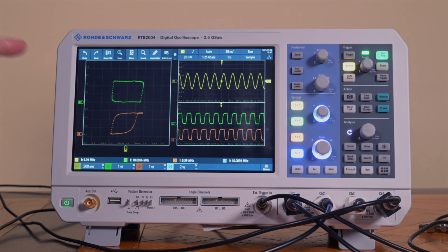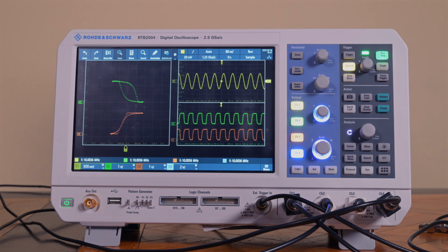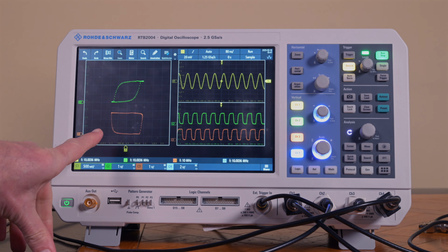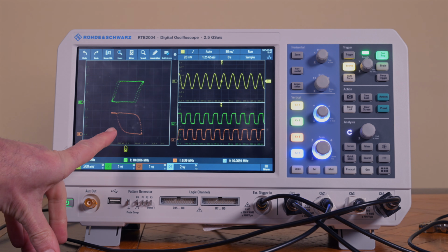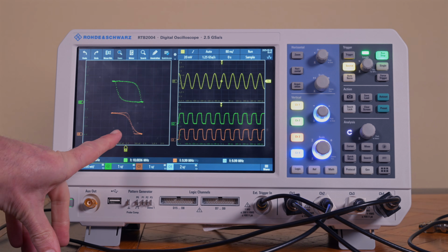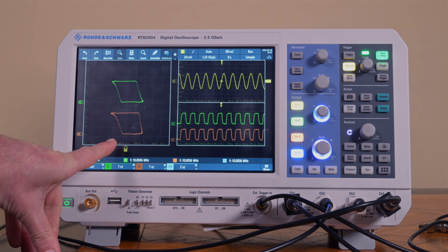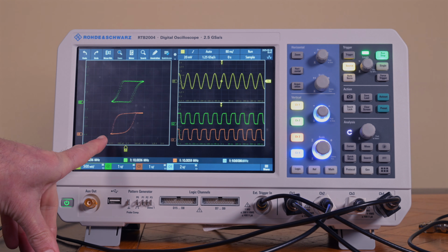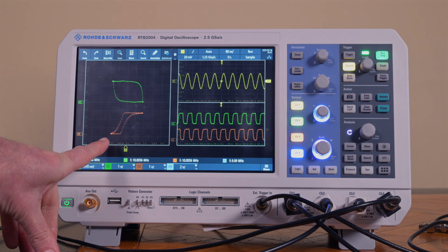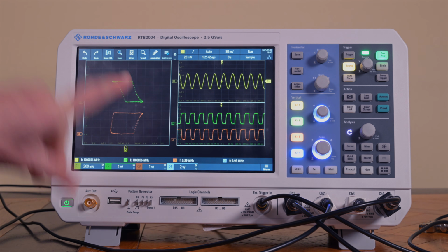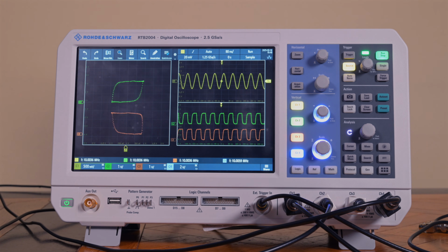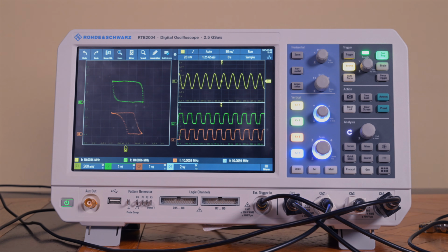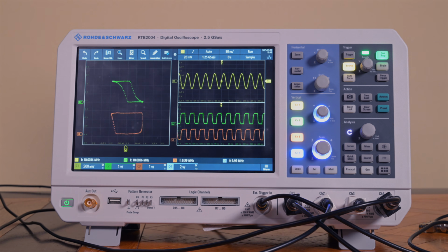Oh, wait a moment, look at this. I was already cleaning everything up and moving my antenna in, and when the antenna of the Bodnar lost GPS, you see it already is way off. That's kind of interesting. You see how it is important that it continuously has its GPS connection. It's continually locking itself to it, and once that is lost, it really gets off its own frequency very fast. So continuous reception of the GPS satellite is really important for the Bodnar.